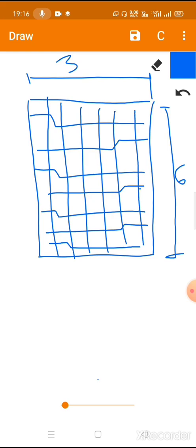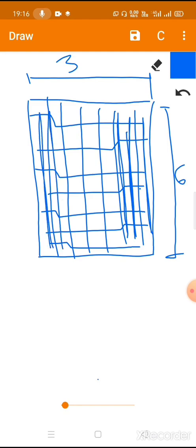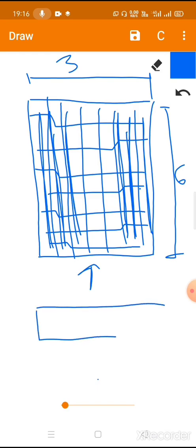Now these distribution reinforcements are laid at the bottom. On the top, on this cranked-up portion only, we have placed 3 bars on either side. So this is how our reinforcement is complete. Now if you look at this from this side, how will the section look? I think this will look like this.